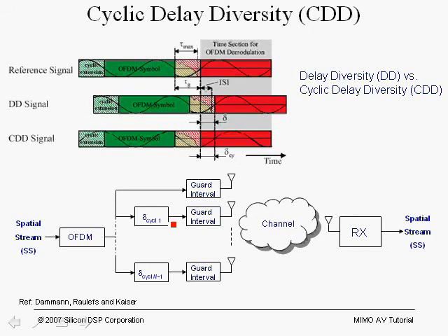Now, if we did not add the cyclic delay in the OFDM symbol, and we transmitted the symbol through the two transmit chains, then there's a high likelihood that at the receiver the signal would exhibit constructive and destructive combination. And this is especially detrimental during the transmission of the fixed preamble, which happens to be the same signal that is transmitted from both transmit antennas. So during the preamble processing, we will exhibit constructive and destructive combination, and the signal will vary.